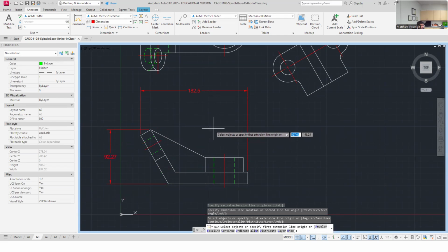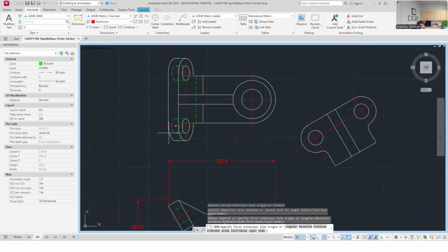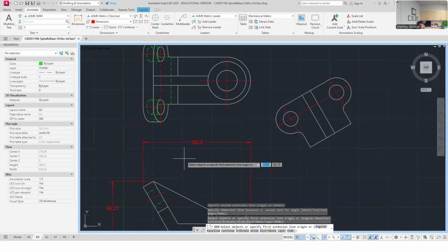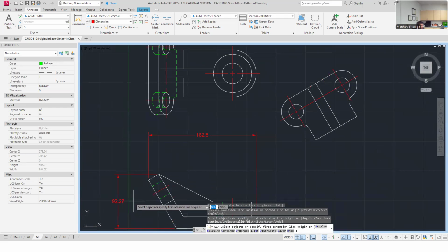I think I'm gonna have some dimensions in here. So maybe I don't want that line to go across initially, but there's height and width. And depth, I think I'm gonna put it up here. I feel like these are good reference dimensions because of the nature of this thing being tipped on an angle, and really you're dimensioning to a very edge here. There might be more critical dimensions that I'm going to hold here than these, just based off the nature of this part. But it's okay. If you see some of my examples and I've got parentheses around it, just know that I've identified that as a reference, nice to know dimension, but not necessarily a critical hold.